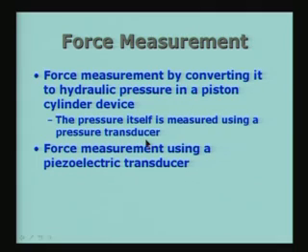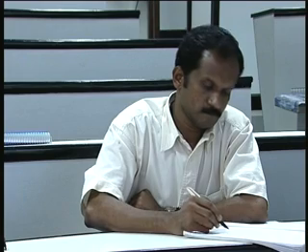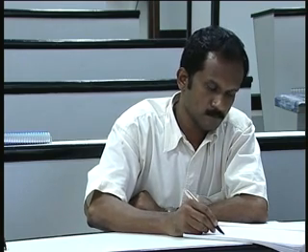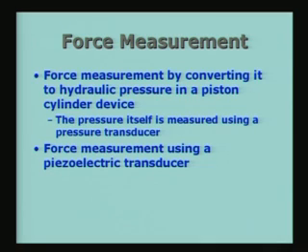Another technique which can be used to measure force is to convert it to hydraulic pressure. If I have a piston cylinder arrangement and I apply force on the piston, it will increase the pressure of the hydraulic fluid which is filling the cylinder. The force divided by the piston area is going to be the corresponding pressure, the pressure of the hydraulic fluid, and this can be measured by using a pressure transducer.